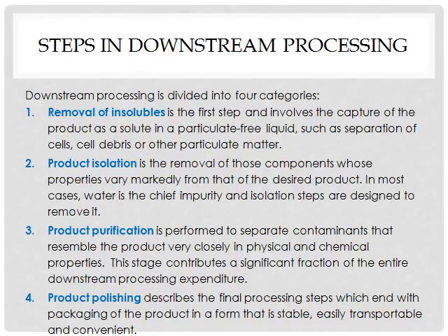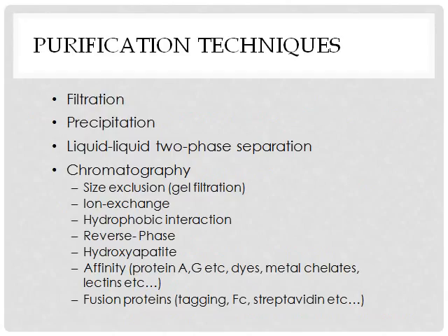And last is product polishing. This describes the final processing steps in which the end product is packaged in a form that is stable, easily transportable, and convenient. Purification techniques. These can include filtration, which is a separation based on molecular size, precipitation, liquid-liquid two-phase separation, and chromatography.